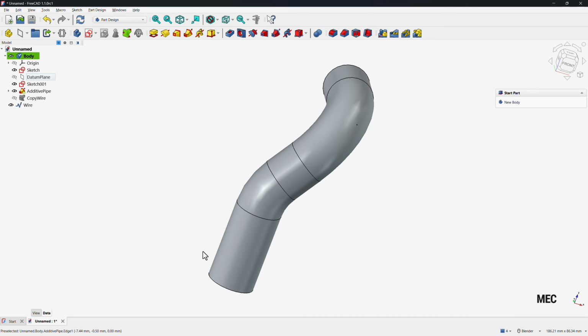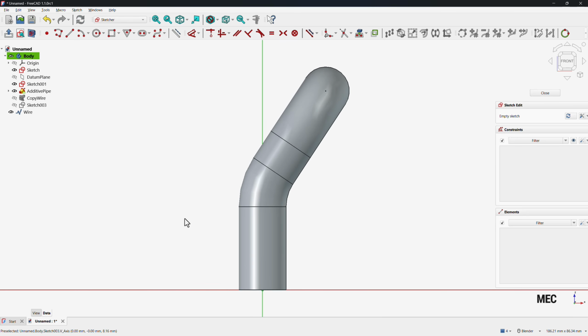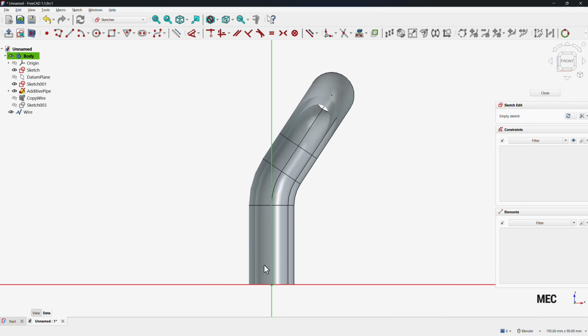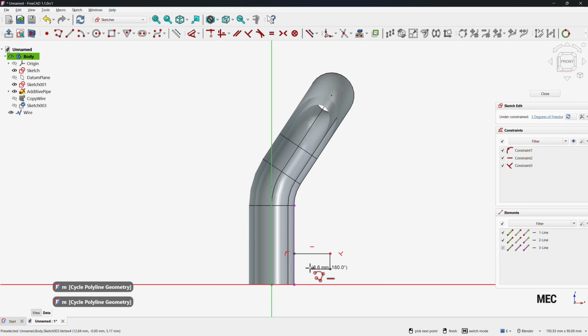After that, we are going to add a flange on the bottom. Create a sketch on the XZ plane. Then go to the section view. And we need to make this edge a reference. Go to the projection and select this edge. Then draw the polyline on this reference. Here we can press the M key to draw the perpendicular line.